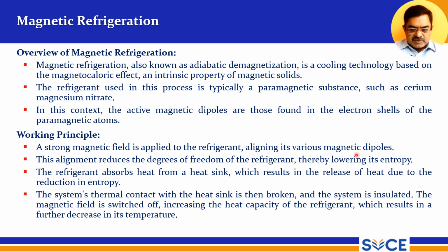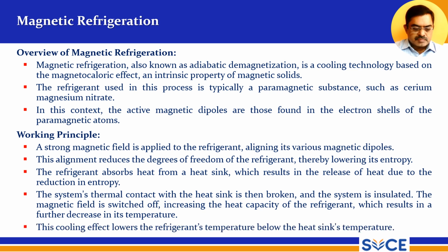insulated. The magnetic field is switched off, increasing the heat capacity of the refrigerant, which results in a further decrease in its temperature. The cooling effect lowers the refrigerant's temperature below the heat sink's temperature. So this is the working principle.